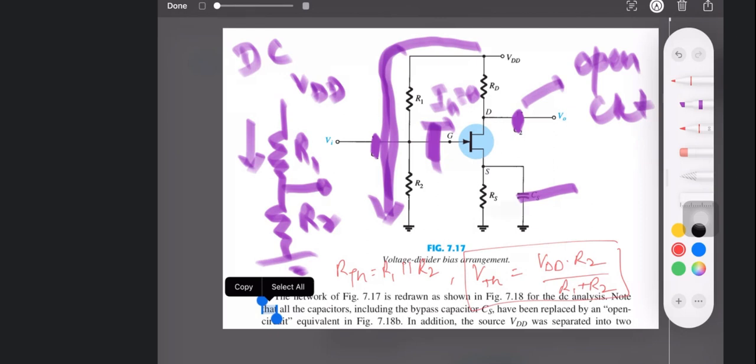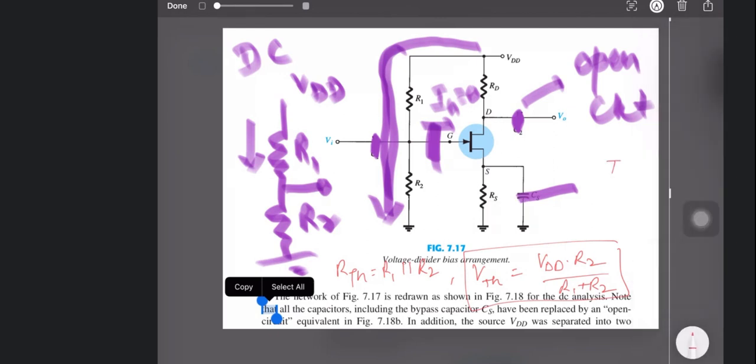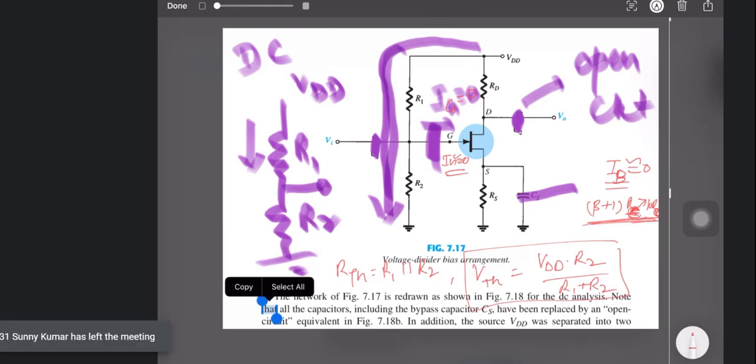Okay. So here, if you remember, in case of BJT, we try to make IB equal to 0. So we have that beta plus 1 RE should be equal to 10 of RE, something like this. We have to improvise. 10 of RC, something like this we have to use. But here, because gate current is already approximately 0, no need for those modifications here.